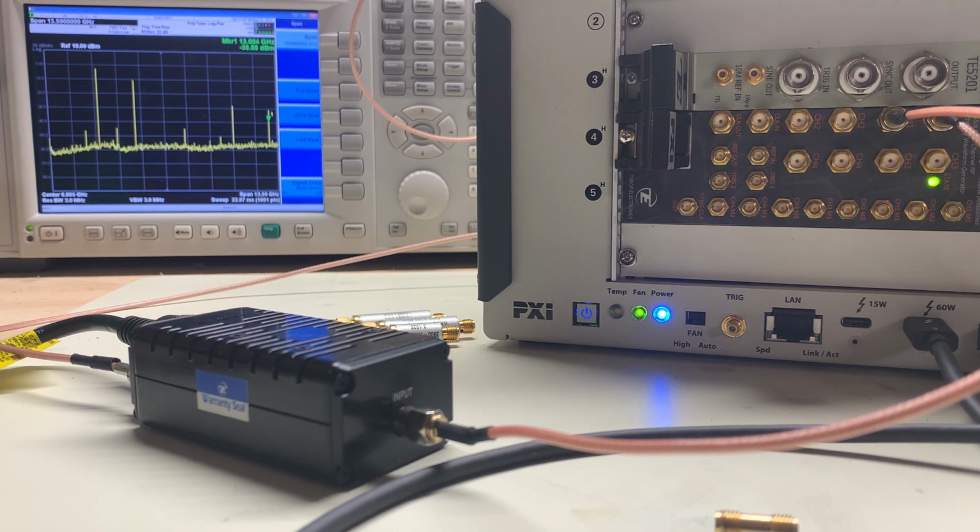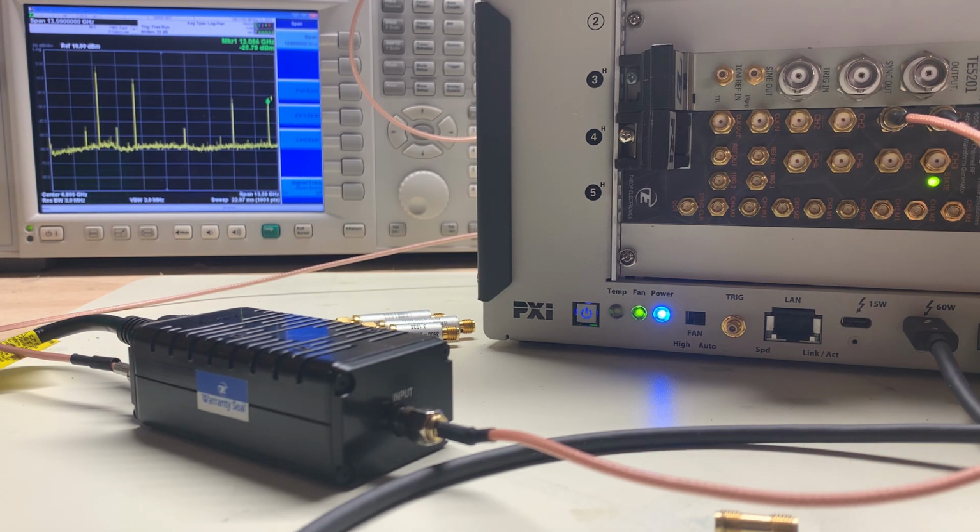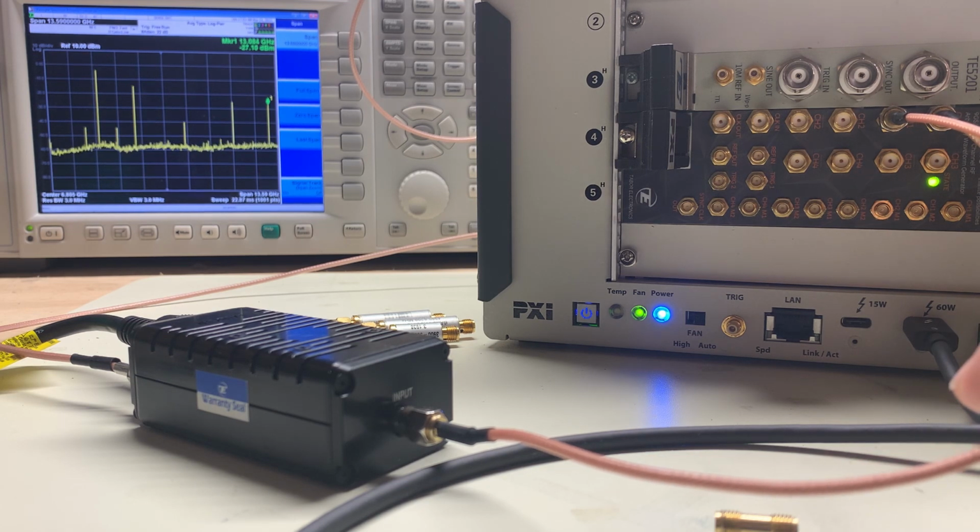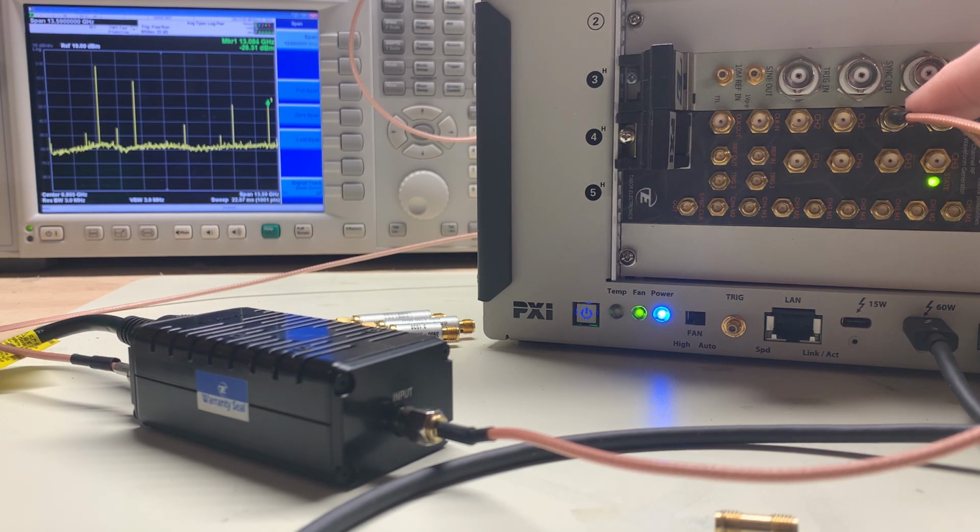We're compensating with the amplifier now because I'm using the up converter within the instrumentation itself. There's no fundamental frequency, so I don't need any filtering. I can just put it straight into the amplifier. The amplifier is very wide band, from a few kilohertz all the way up to 20 gigahertz, so there's no problem in terms of amplification and headroom with this thing.